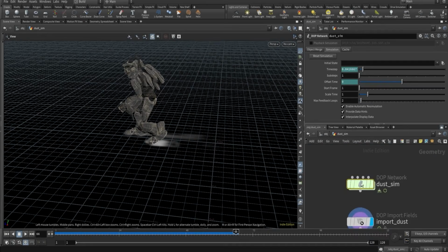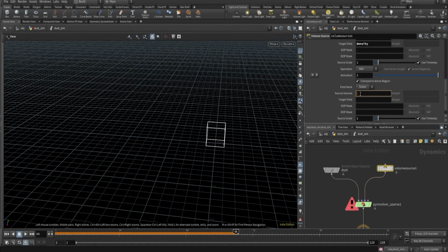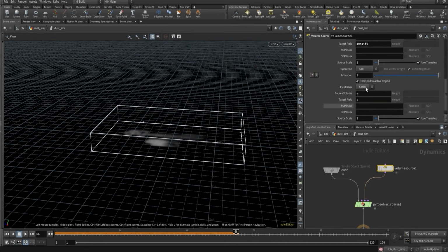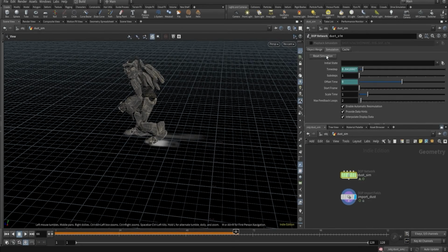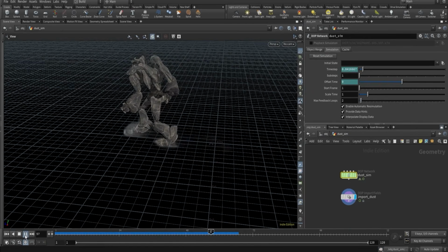Now let's dive inside. We have to make sure that we read that velocity over here. So if I type V and V and it's a vector, will it work? Still it won't work. Pyro Solver doesn't understand V. So what it understands is vel. So we have to make sure we properly type these things over here. And now if I check this, reset this, awesome, that's working. So an object in motion stays in motion.